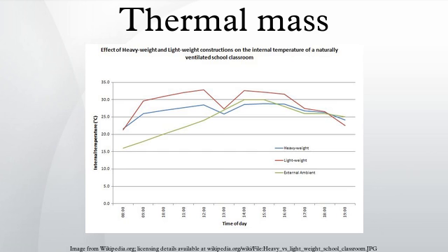A table of volumetric heat capacity for building materials is available here, but note that their definition of thermal mass is slightly different. Use of thermal mass in different climates: the correct use and application of thermal mass is dependent on the prevailing climate in a district.